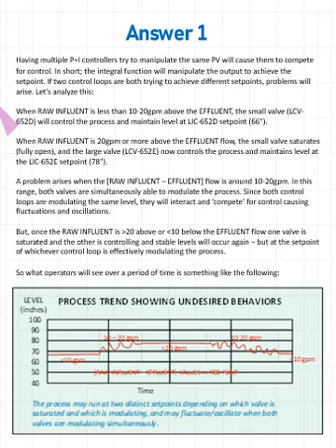If the mismatch is greater than 20 gallons a minute, then the large valve is fully in control, and it's going to basically get this process up to 78 inches and try to keep it there pretty stable until at some point the mismatch drops down in the 10 to 20 range. You get oscillations, fluctuations, and so forth until it either returns to above 20 or below 10, at which time it either picks 66 or 78 inches and stabilizes again.